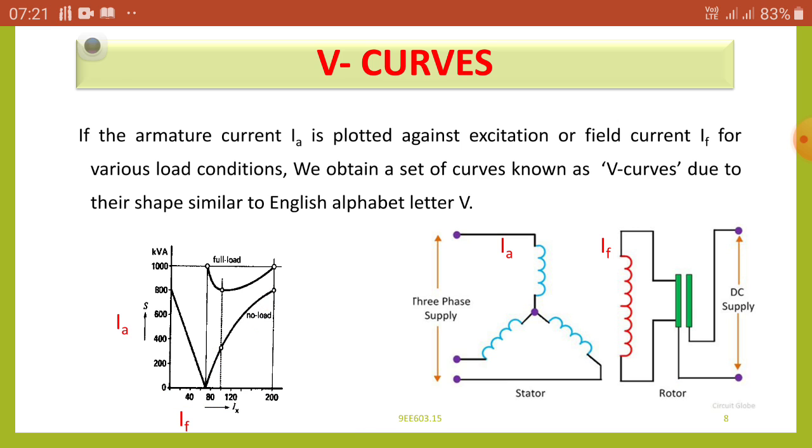For this experiment in the laboratory, we require the synchronous motor and a pony motor, that is an induction motor, to start the synchronous motor initially.